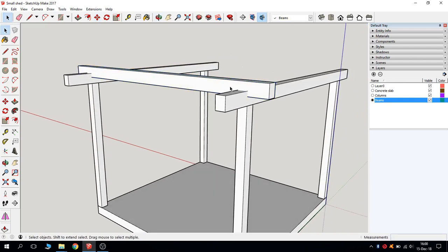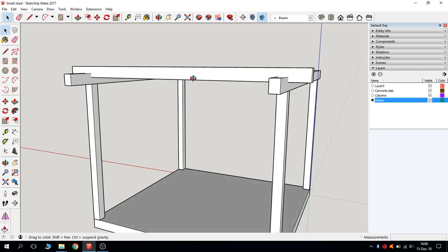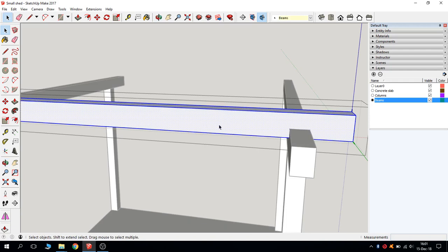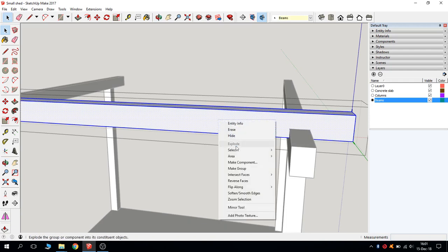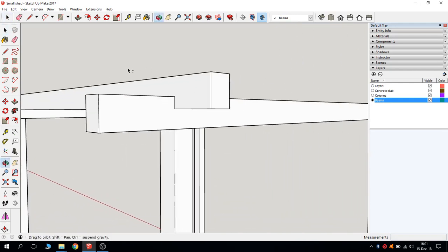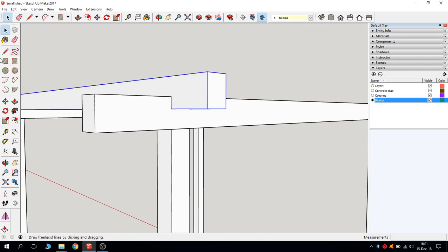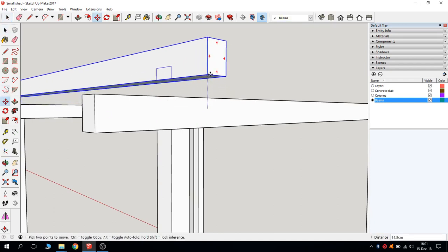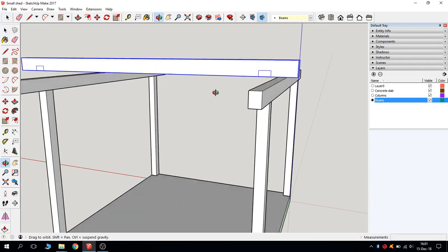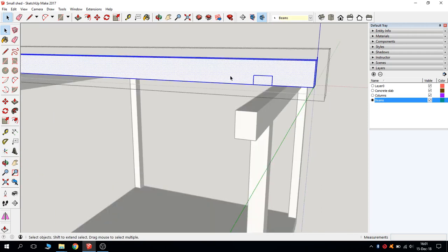Okay, now we need to cut this beam, so we're gonna open it, this beam, then select it all, intersect faces and with model. Now what it did, it created these lines that you wanna see, so we can move this up. You see it created these lines here. Now we're gonna delete this part of the beam, so open it, select this and then push pull, and when you get this warning it means you delete it.